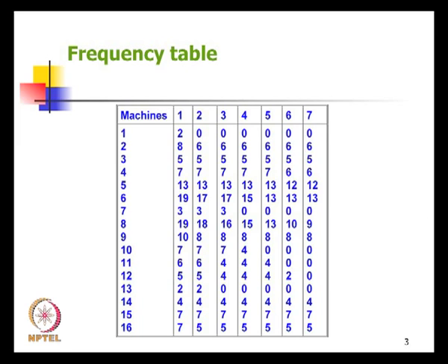So we continue to create these modules, and as we create these modules we observe something interesting. Now at the end of every column here we create a module with the nucleus machine as the machine with the smallest non-zero frequency. So between columns 1 and 2, the nucleus machine in column 2 will get a frequency of 0. In column 3, another machine which was the nucleus earlier will now have a frequency of 0. In column 4, some other machine will have a frequency of 0. So every column now has one additional machine having a frequency of 0.